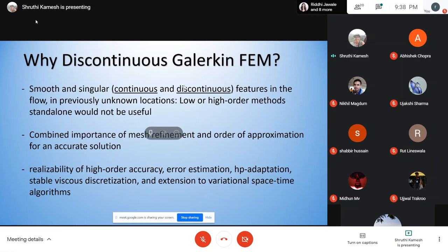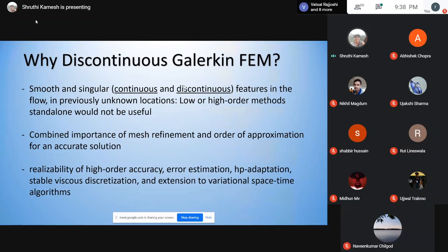So using a very low order solution, say finite volume over like 10,000 elements, or in many cases people go up to like 100 million mesh cells, you're not going to get anywhere. You would have the same resolution. You would not have more detail, not necessarily the details that you desire. So increasing the order of approximation is very much important, especially for a very critical problem.